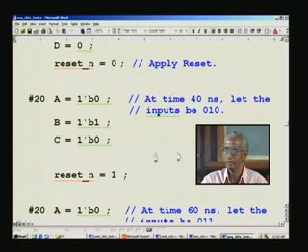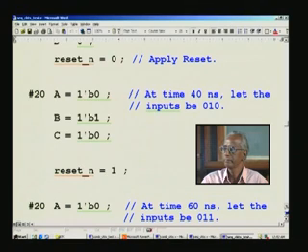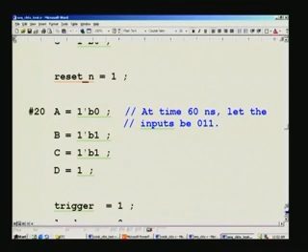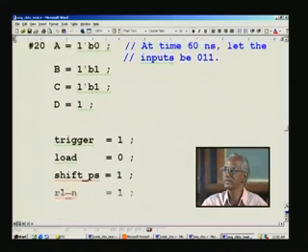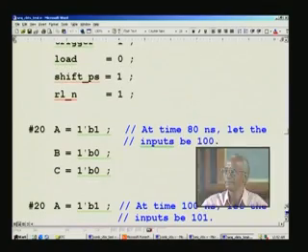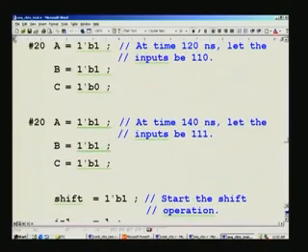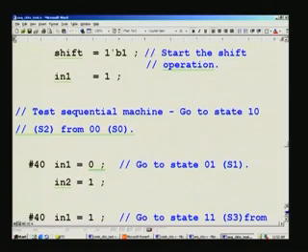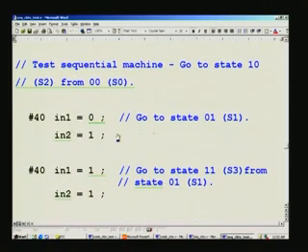When we see the simulation we will see that exact timing, that you can find out because that clock variable we have given, we have made it 0, we will come to that later on, when it will change we will see. So, that determines the rising edge of the clock. It was 0, then when you make it 1, so naturally a rising edge is encountered, and similarly you keep on changing for various inputs. So, that is what you see here. And this is for the sequential machine, basically in 1 and in 2.